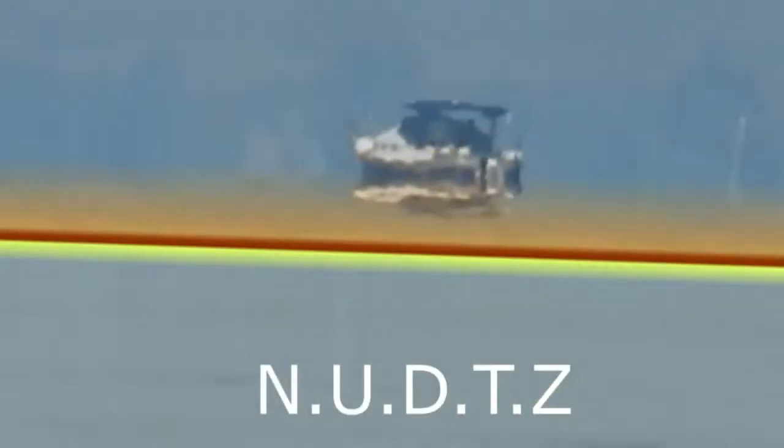Placing the laser close to the water surface increases the problems with the refraction caused by what we call the non-uniform density transition zone, or the NUTS. It is a zone just above the water surface. It is ideal to place the laser at least 7 feet or 2 meters above the water surface to avoid this area of light disturbance.